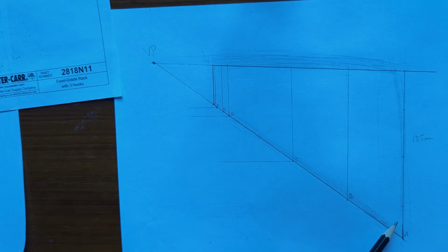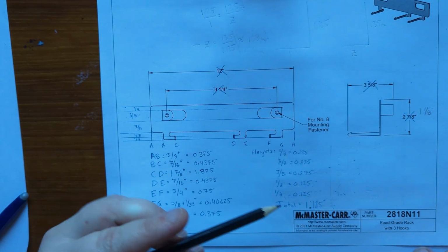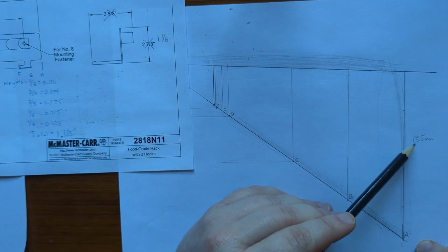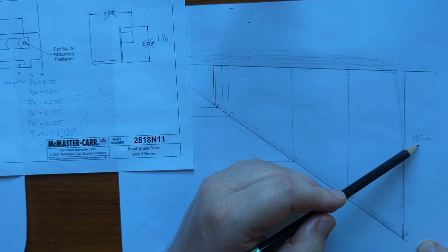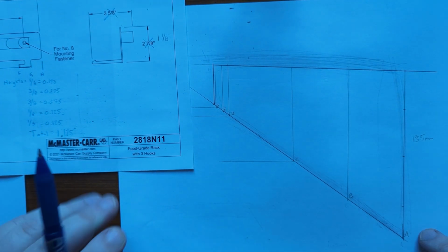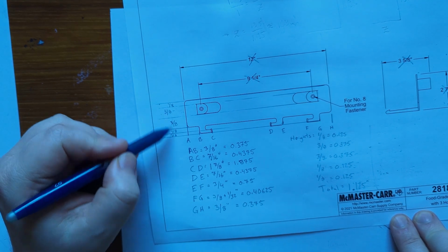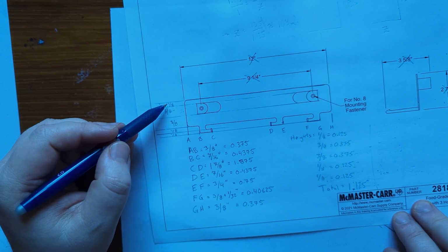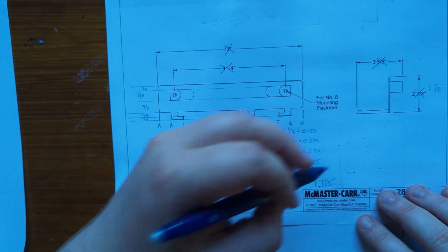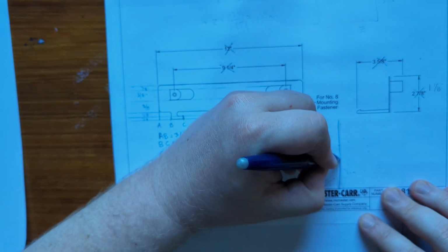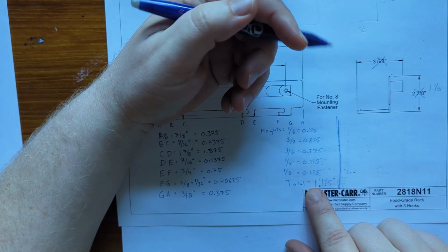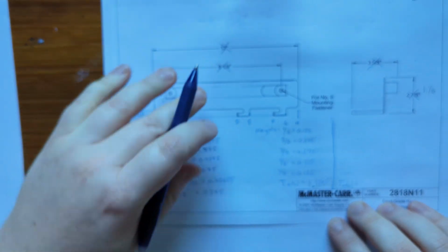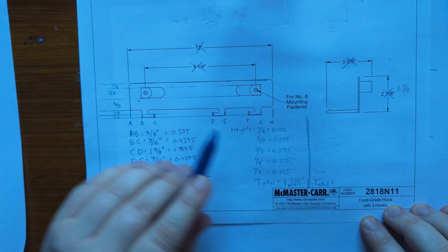So looking back at my drawing here, I've got all of these heights that all add up to 1.125 inches. And then in my drawing, this total height is going to be 135 millimeters. In order to figure out how these heights, again, there's no foreshortening happening. We're just going to be making a set of ratios here. So what we want to do is figure out our conversion factor. So I'm going to make a second column here for my heights, so we have these real dimensions and the drawing dimensions.